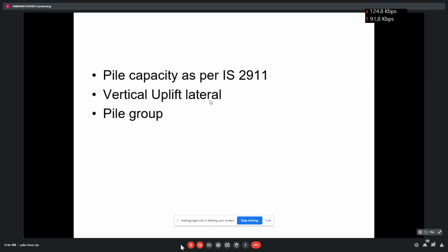Then we go for pile foundation. So when the top soil profile is not capable of taking the load from the superstructure, we are transmitting the load to a deeper dependable soil profile, to pile. Now, what projects will generally go for pile?